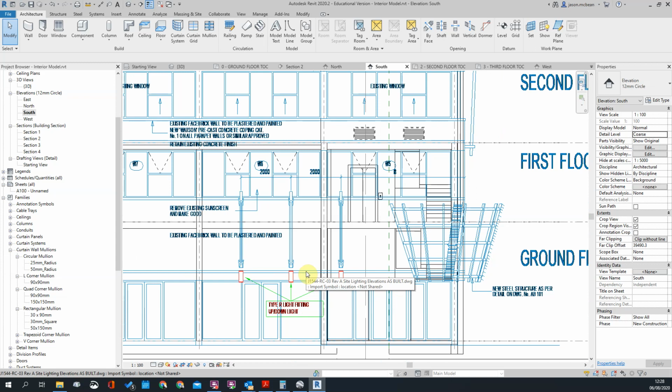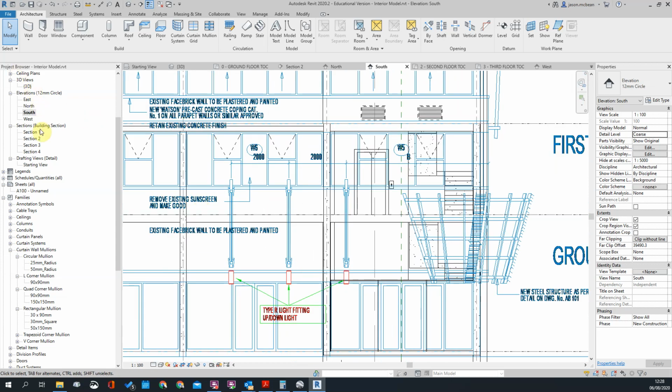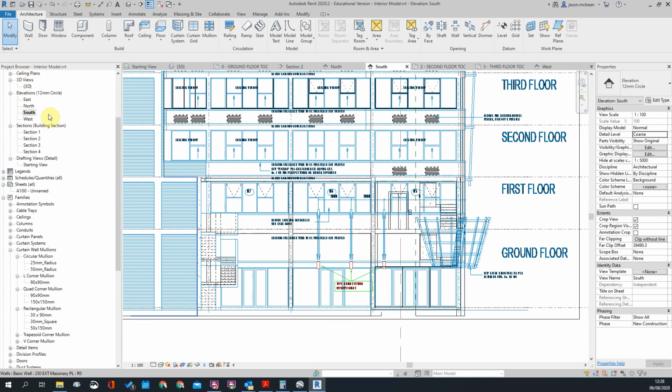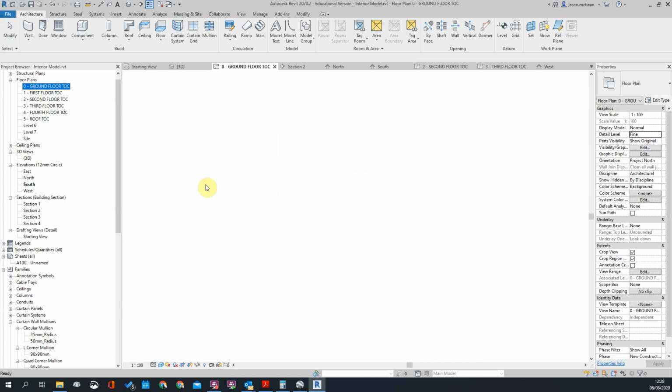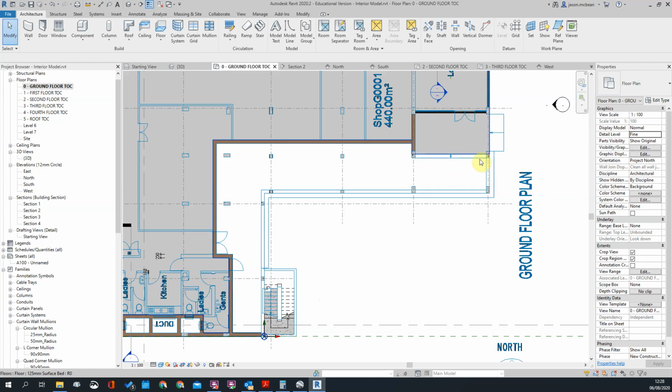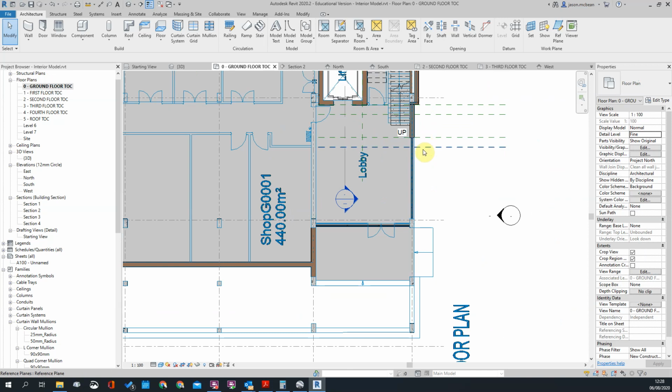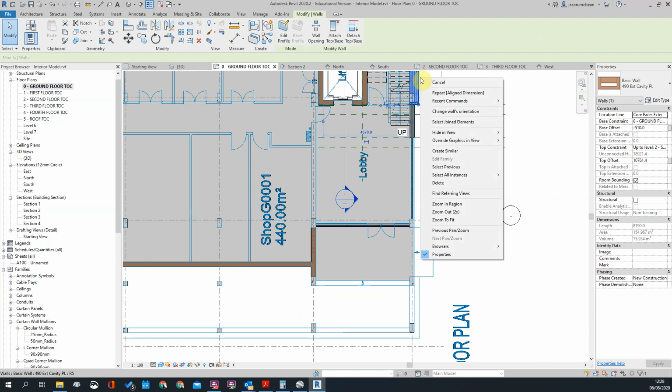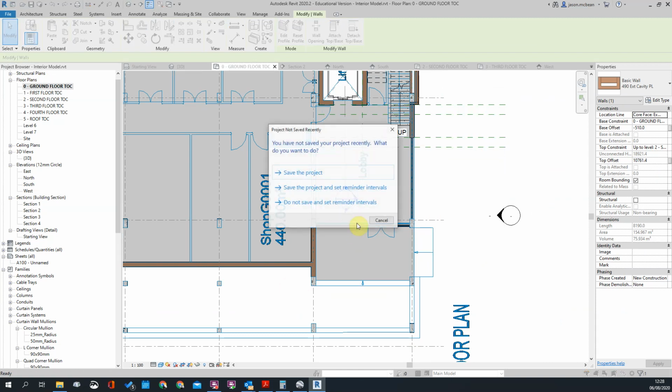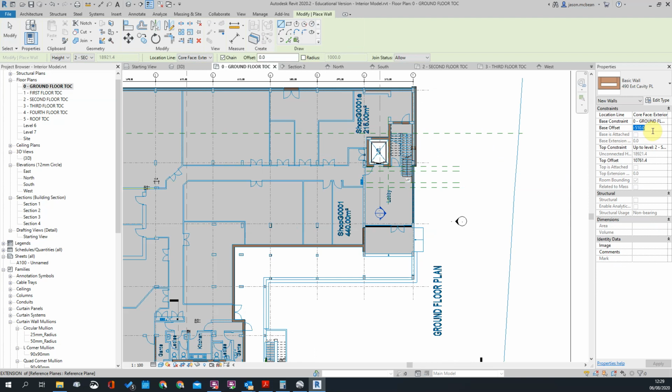Okay, I'm going to assume that this is like a detailed feature wall, and I'm going to do this on my ground floor, but I'm going to offset the wall quite a bit. So in essence, that wall sits above these columns and probably goes all the way around over here. And I can see that this line kind of ties in. So this wall actually goes from there, goes around. So I'm going to create the same wall type, so create similar. Okay, but I'm going to offset this by 3000 from ground floor, and it goes to first floor, and probably by 1000.